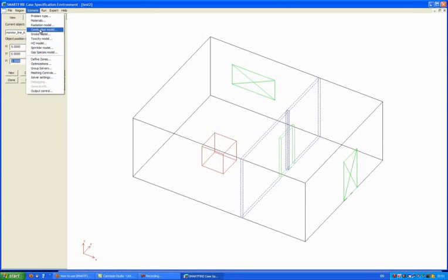Module configuration: if you know more about the particular type of fuel or smoke, the defaults might not be appropriate. This is particularly important also for the toxicity and HCl model, where it's very dependent on the nature of the fuel and the nature of the combustion. So do take some time to consider the options available and what is appropriate for the particular simulation that you're about to run. The other important option for configuration is the output control.